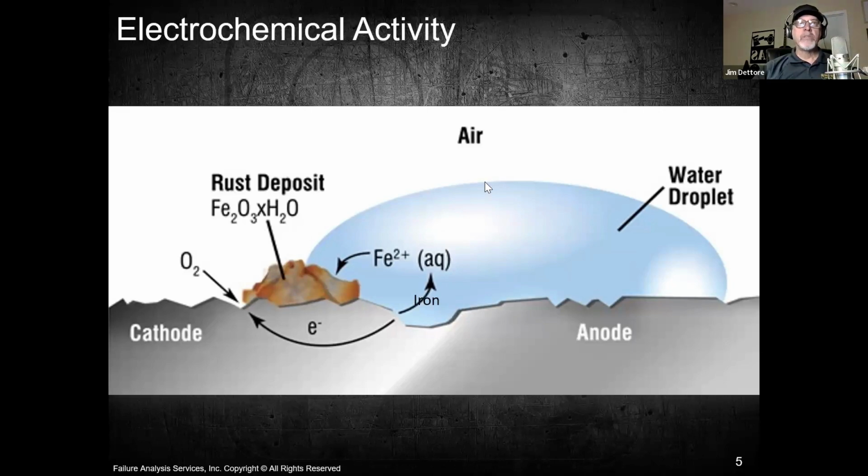When H2S combusts in the combustion chamber, it's interesting that at temperature, it doesn't only generate sulfur dioxide, but it also generates its own water, which accelerates the corrosion. So now you've got an electrolyte plus the corrosive constituent. So when we see H2S related failures, boy, corrosion is pretty severe. It really likes to attack yellow metals such as copper and bronze alloys and things like that, brass.